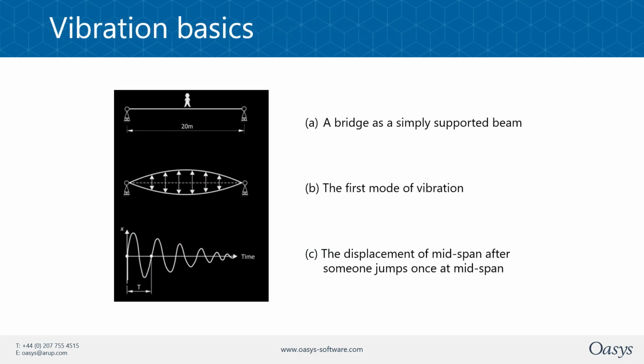So, vibration basics first of all. When people walk on the surface, on the floor and so on, it creates an impact force. People tend to walk at a given pace. The frequency of these impacts can set up resonances in the structure, working with resonance with the natural frequency of the structure, causing it to vibrate and shake and so on. And there are also transient effects, momentary vibrations from footsteps.